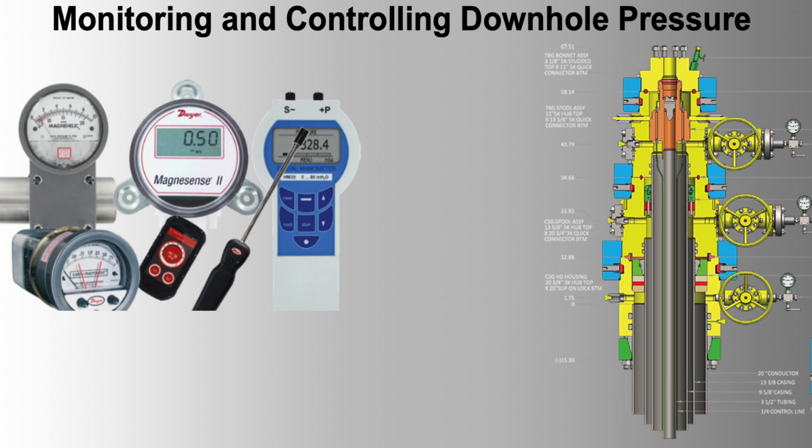5. Issue: overpressure events during production. Problem: overpressure events leading to equipment damage and safety risks. Solution: implement automated control systems that can quickly adjust choke valves or alter flow rates to maintain safe pressure levels. Use predictive analytics to anticipate pressure surges and take preemptive actions.